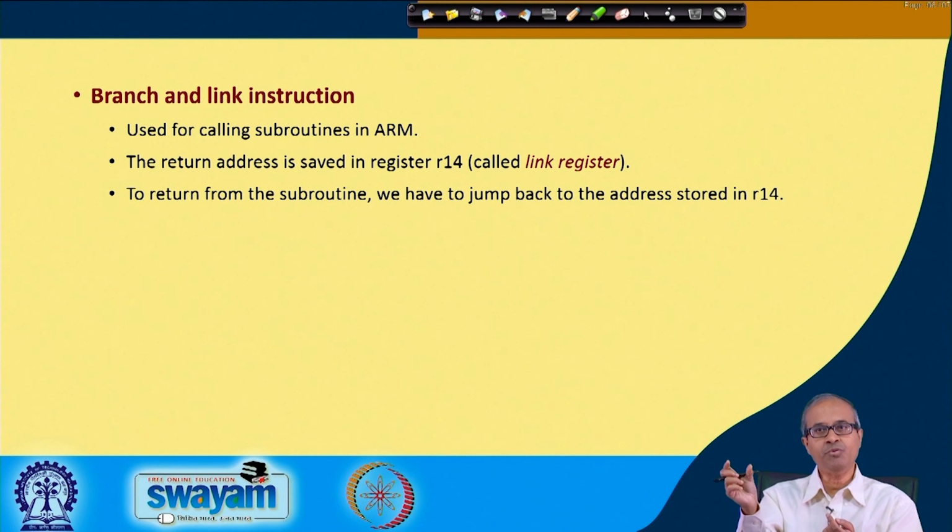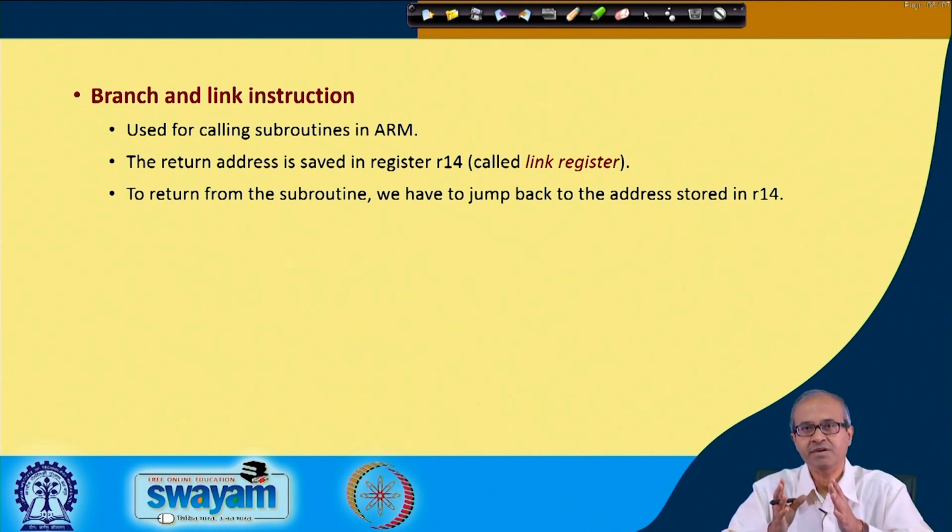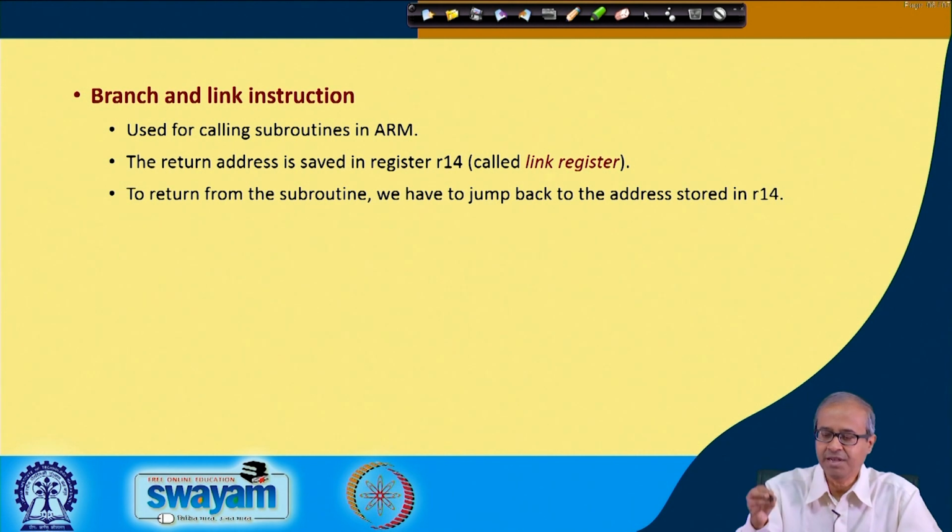What will the return do? It will pop the last element from the stack and load it into the program counter, which means you return back to the program, to the instruction after where the call instruction was executed, because the PC always points to the next instruction, right. So, that is how things are handled in a conventional processor.